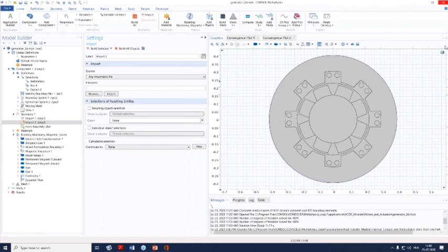In that case, you can say that if that parameter value is set to L equal to 1, execute one part of the code. If the parameter value becomes equal to 3, automatically COMSOL will decide which part of the geometry code should get executed, and accordingly the boundary conditions and the physics will be set up.